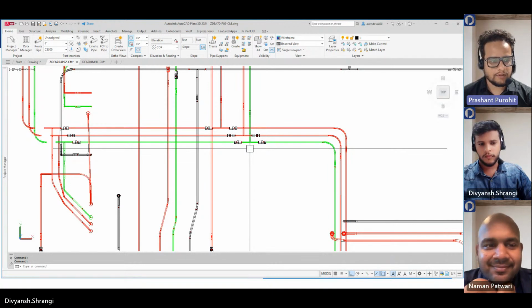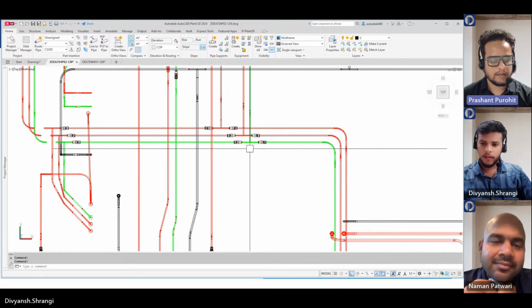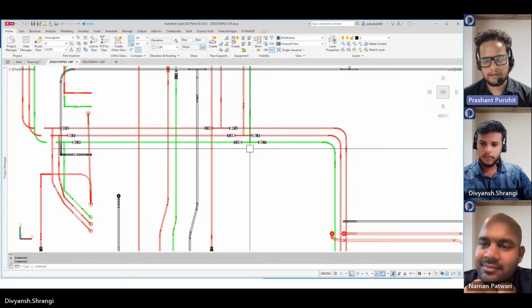Before that, we used to do manual tasks and provide weld ops at each location for the field welds and shop welds. And now using that particular plugin, we are providing them in a single click at every field weld and at every shop weld. And we can also adjust the properties of that particular weld sphere, be it the color or the size of it.